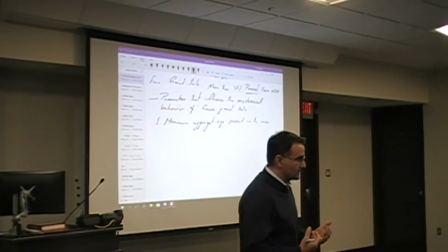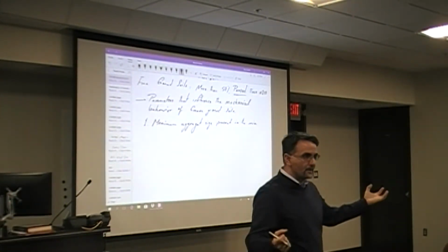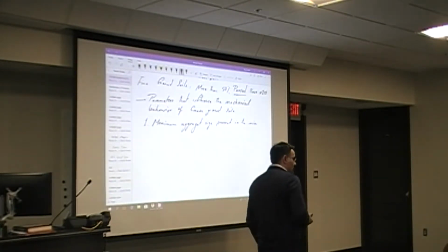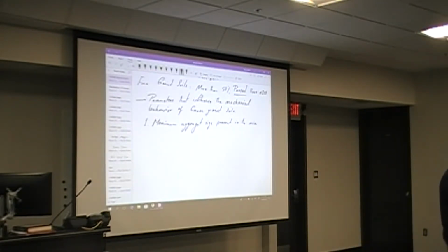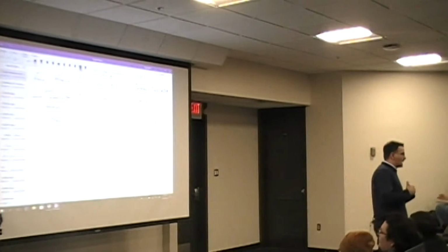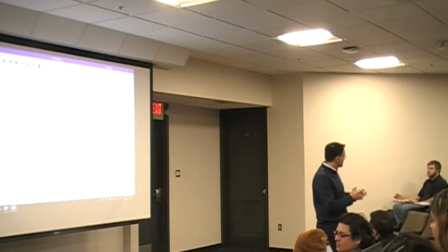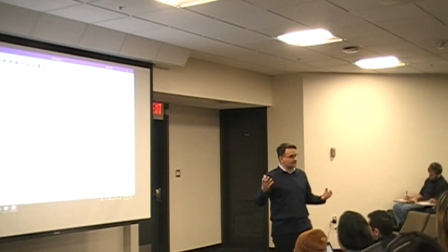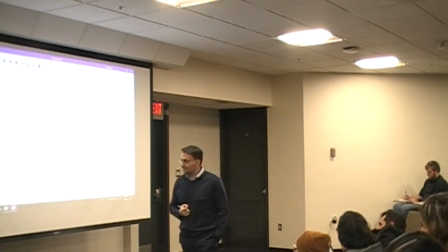Think about it intuitively. You have very fine soils and you have big chunks of aggregates, right? If I have fine grain soils, and I go there and stick my foot there, I can see my footprint right underneath it, right? So the deformation characteristics are not going to be as desirable as coarse grain, solid soil, right? So the larger the particle size, the higher the stiffness properties. This is the way that you can essentially correlate it and understand this. So the first one is very simple and very intuitive.